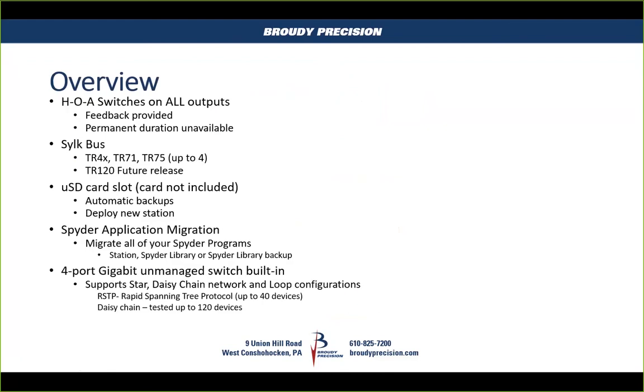There's hand-off-auto switches on all the outputs, and there's a status point for each one, so you do have feedback if somebody goes up and flips the switch, or turns the pot on the analog outputs.